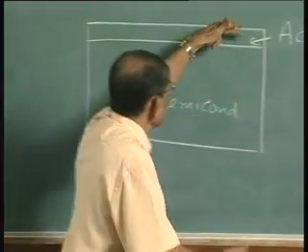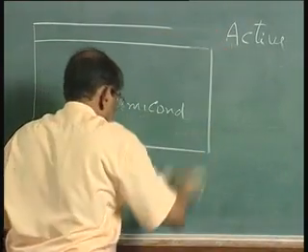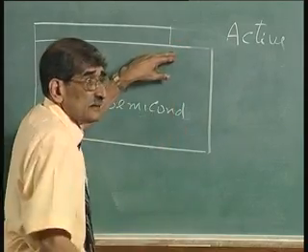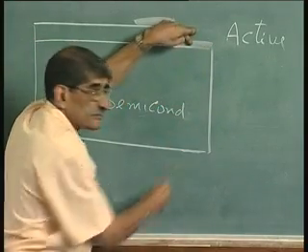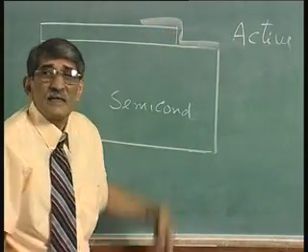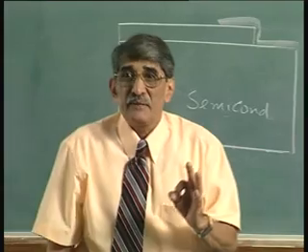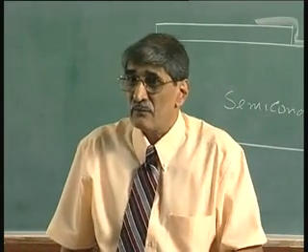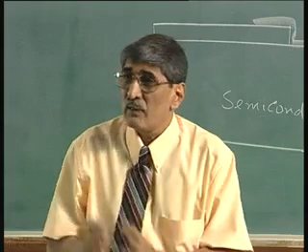For example, when interconnecting, I can remove this layer, so the interconnection goes through like this, and that is the capacitance. With a thick layer, the capacitance is very small. So, this is one of the key things in high speed devices and high speed circuits made out of high speed devices. This is why people are looking more and more into substrates which are insulating.